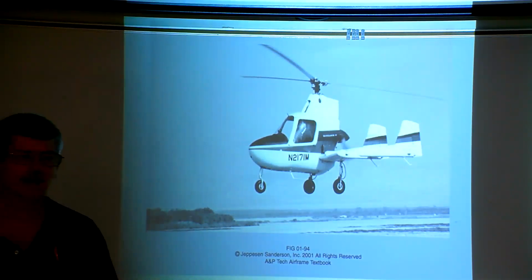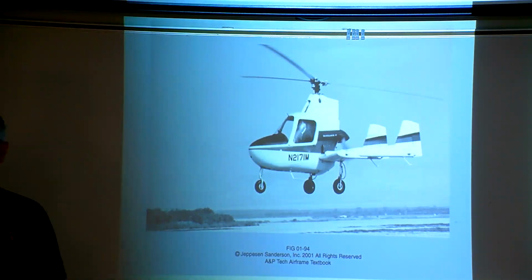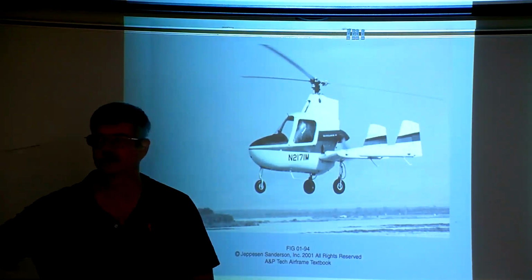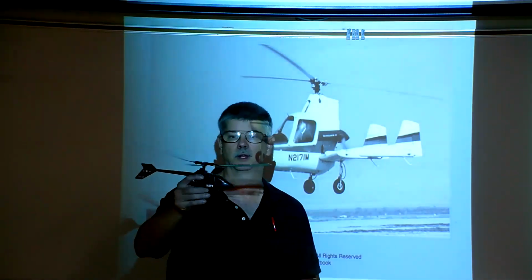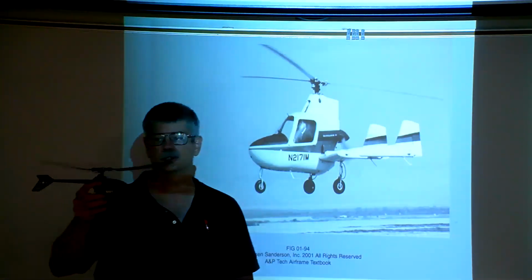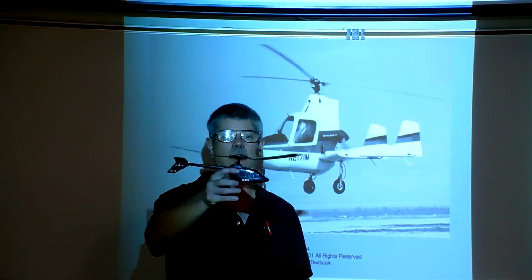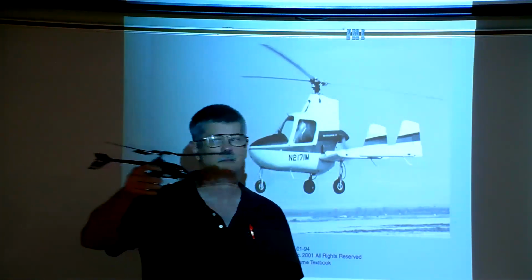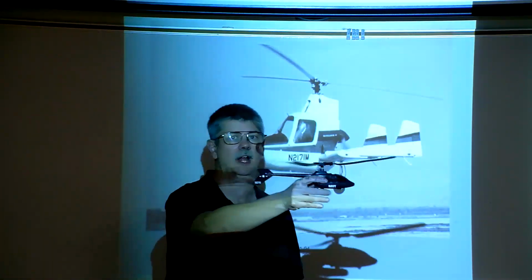It is powered by the aerodynamic forces flowing through the rotor, so it does what is referred to as autorotate. Now, as long as the aircraft is moving forward, the rotor blades will spin. As long as they're spinning fast enough, the aircraft can ascend or descend, or they can stay in level flight.